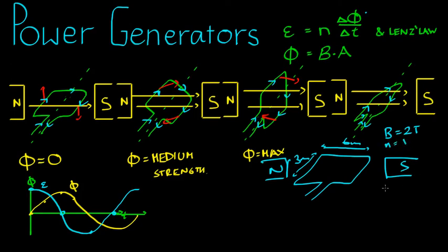And it's spinning. The total time it takes to complete one revolution is 16 seconds. So one full revolution like that. Let's figure out the average voltage being induced in this wire here. So first of all, we pick 2 points which the loop could sit in. The first one I've drawn in blue, and the second one in green. So you can see how that loop would move up like that.